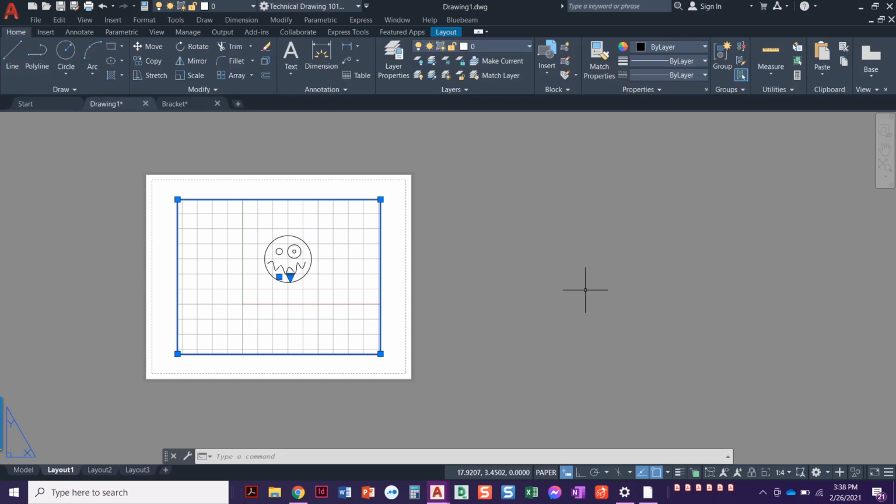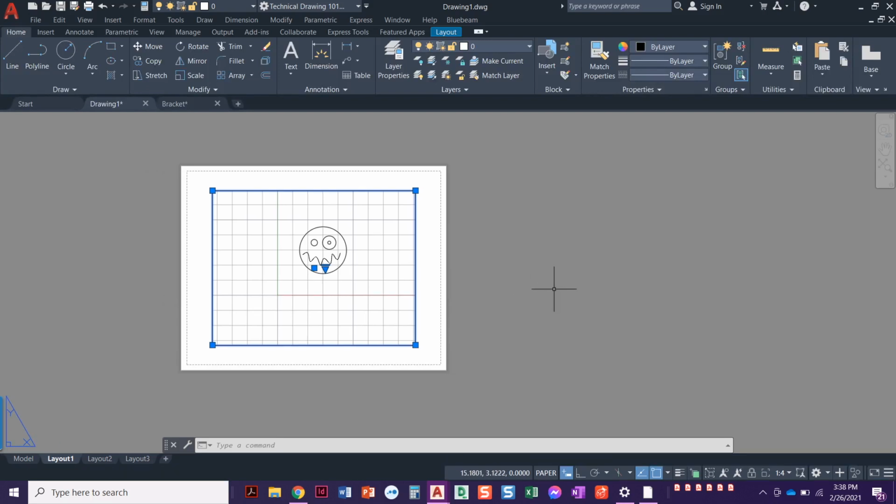But what I want to show you, and this is the really important thing, is that when you set that to say drawing scale 1:1 or drawing scale 1:2, those are actually your viewport. We call those viewport scale 1:1, viewport scale 1:2. 1:1 is full size. 1:2 is half size. 1:4, it's a quarter size. If you print this out right now and you lay down a scale and measure this, this will actually come out to be 1:4. It'll be a quarter of the size that it was originally drawn. You have truly scaled this thing down. That is why viewports are so important. We can set true scales and actually measure objects based on that.